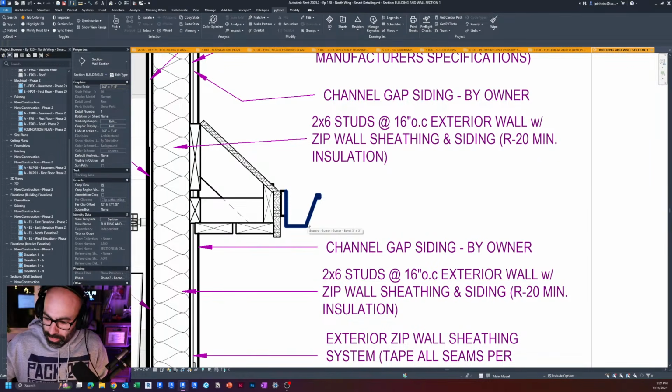Okay, so what that means is, with every element, the multi-category tag pretty much works on every element in Revit. There may be some limitations, and I can go through with a list, but honestly, every element, and that includes detail items, not just 3D items, okay? So you can use the same tag type for your 3D elements, your system families, like your ceilings, walls, doors, your in-place or family components that you brought in, as well as your detail items, okay? Except for insulation.